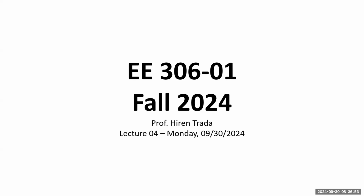The reason I stress a lot of importance on Thevenin Norton is, well, it's very important in the field of electrical engineering, but specifically for this course, when you deal with circuit design and circuit analysis using diodes, transistors, you should be able to perform a quick setup, within a few seconds or a few minutes, of your diode or transistor circuits. For example, there might be 3 or 4 resistors in front of a transistor, and you'd have to find the equivalent Thevenin resistance as seen by the transistor.